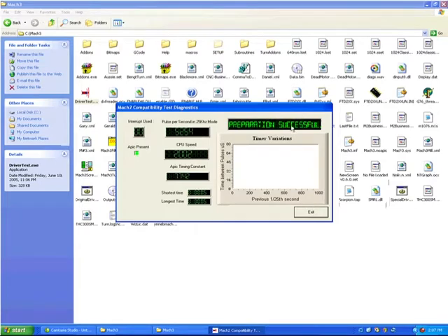If you get a waveform which is terrible, one which is not a straight line like this one gives you, but large spikes all over the system, or you may find you've got noise going up to this level and just periodically messing up your waveform, then you need to run a file called optimization.txt. This is a text file which has several steps in it which can help you to remove processes in your computer that Mach3 is having a problem with. There are several things in the list, and you can either contact me for the list, download it from the website shortly, or get it from the Yahoo support group.